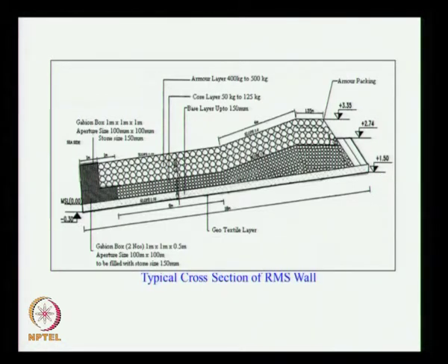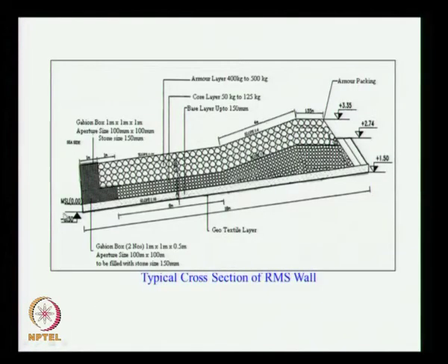If the tidal difference is larger, then the width has to be increased so that this level is above the highest high water level. Here mean sea level is 0.0. In Kanyakumari district and other places, the tidal variation is about 0.6 meter, right. That means this will be approximately your low tide level, and 0.3 meter above mean sea level will be your high tide level.